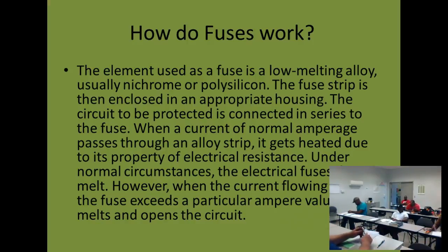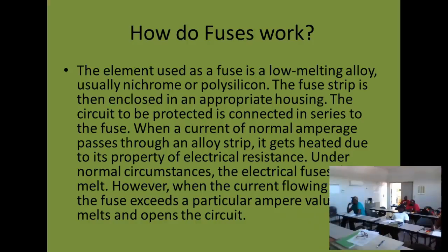Now, did I say anything about path? I didn't say anything about taking voltage on a path. And so a lot of times people think they can accurately use their voltmeter across a switch. All right, we know there's voltage flowing through this switch, or the light wouldn't be on. I know there's voltage there.